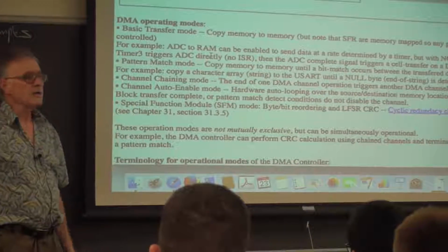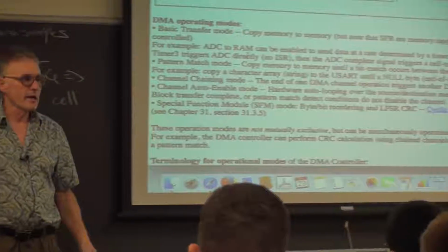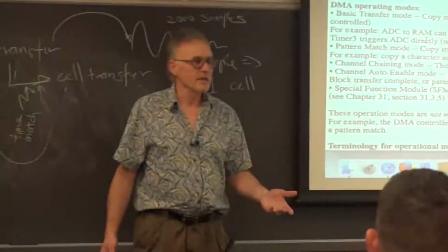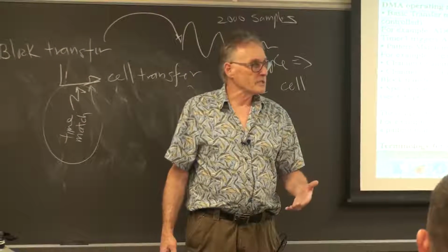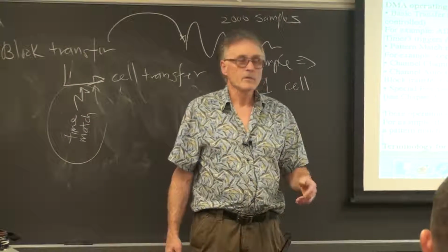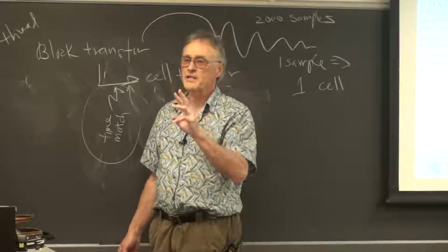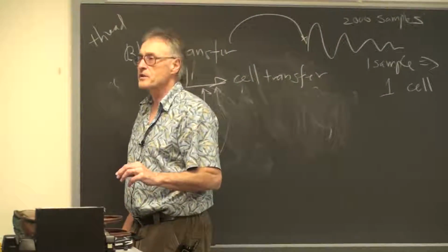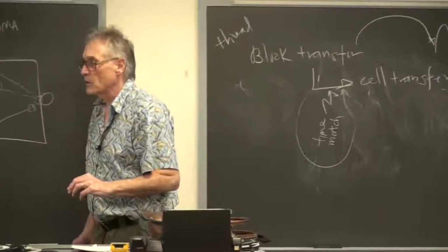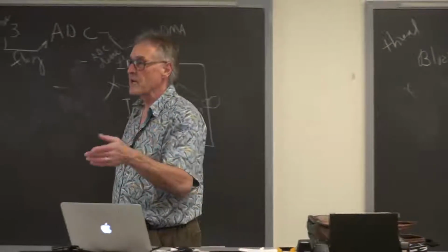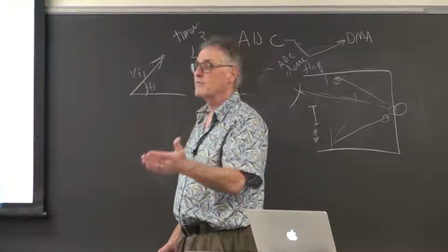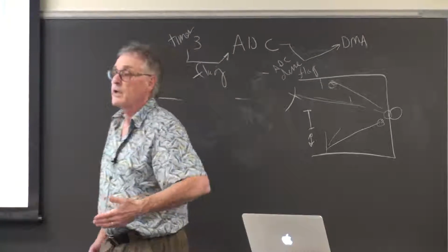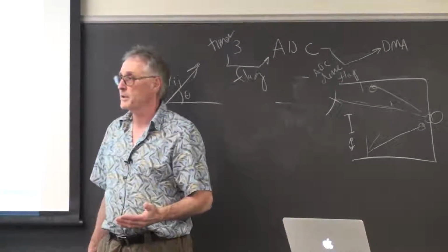Why would you do that? Well, let's say that you want to generate a periodic signal like a sine wave indefinitely. You build a table with the sine wave values. You start it with a block transfer. If the block transfer is on auto enable, when you get to the end of the sine wave buffer, it starts again and just keeps going, playing the sine wave cycle over and over again. In other words, you get a never-ending periodic signal.